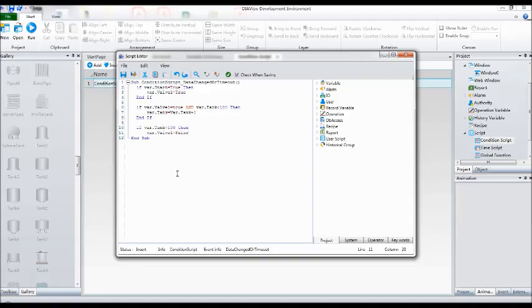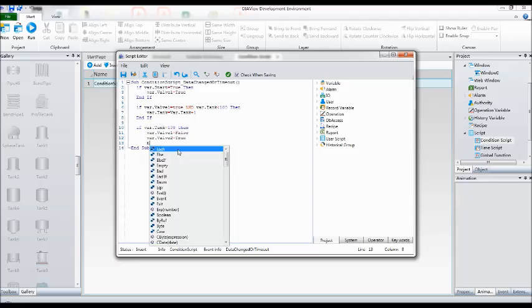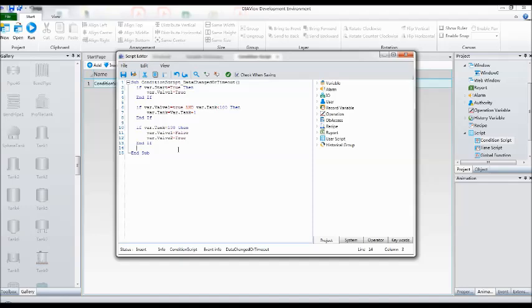And what is the other requirement? Variable val2 should be true. That means the second valve should be blinking so that draining will start. That is end if. When the tank is full, I am going to switch on val2. That is what val2 being true means. So I am writing one more condition now.